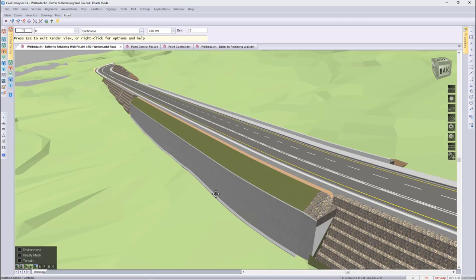Thank you, Charles, and welcome everybody to today's road webinar. I'm excited to show you the powerful point control functionality. Simply put, point control is a point that is indicated in the cross-section of your road template. You are then able to modify that point horizontally and/or vertically, targeting a CAD entity or an existing road string. This then allows the location of the cross-sectional point to be moved as per your rules specified.